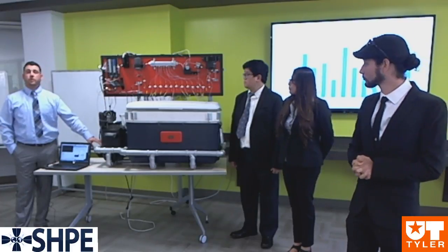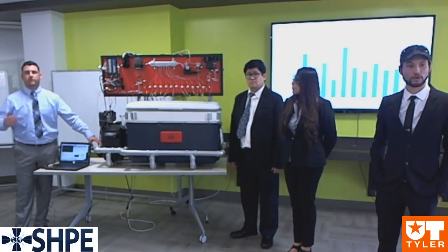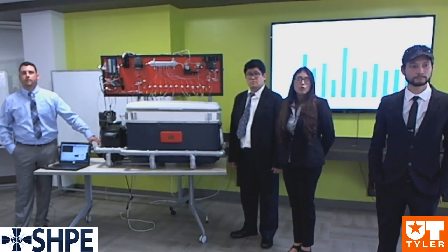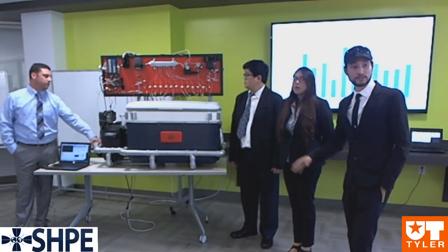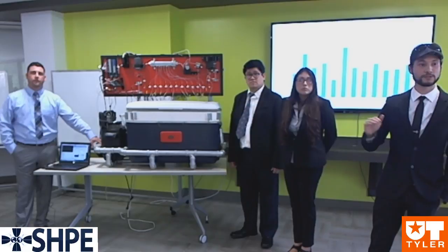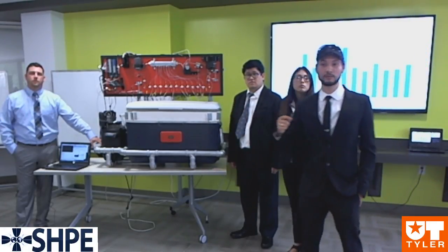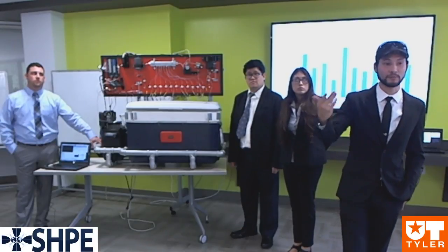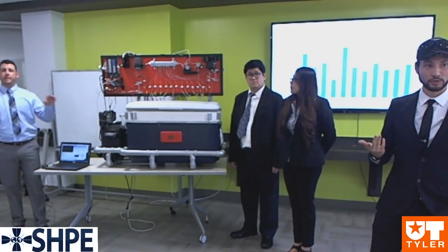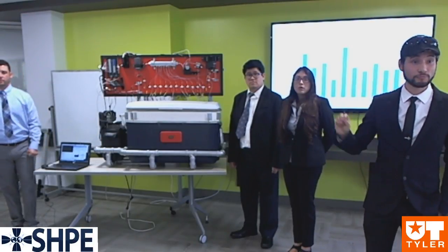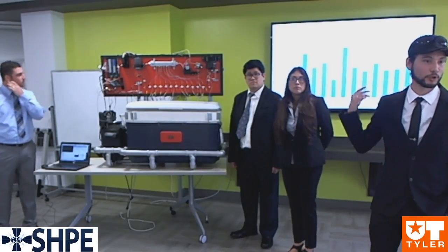This system constantly runs. It's constantly cooling. It doesn't kick on and off as needed. It's always running. It's working hard. So it's not on-off control. I'm asking, so what kind of control are you using? No, the system runs all the time. It doesn't have a control. The only thing it has is a thermocouple to tell the person what temperature it is, so you can monitor it visually. Oh, so there's no controller, but it runs very stable at 30 Celsius, as we showed you in the graphs. Yes.